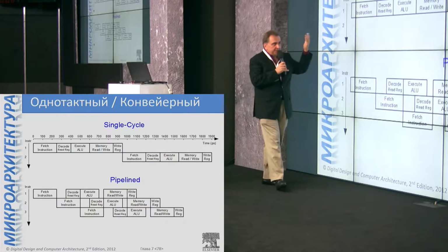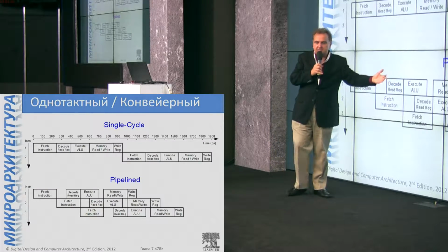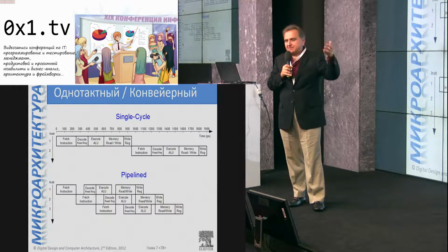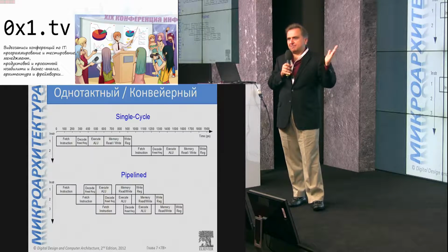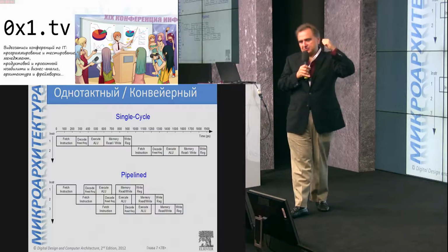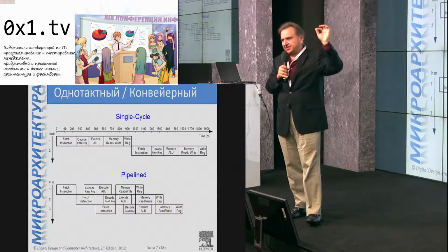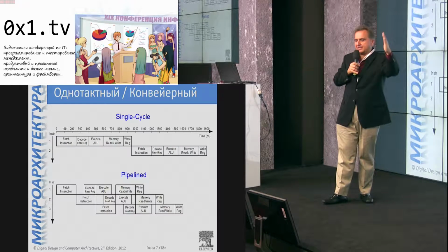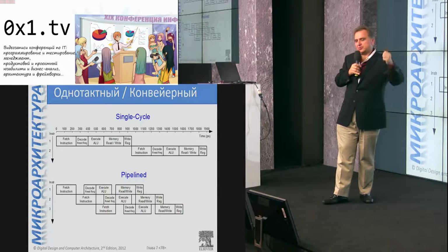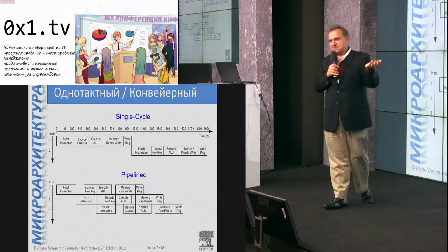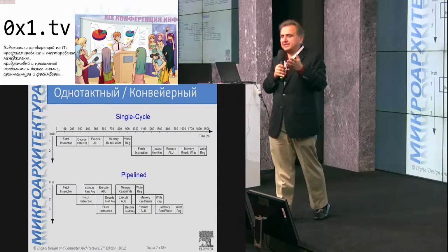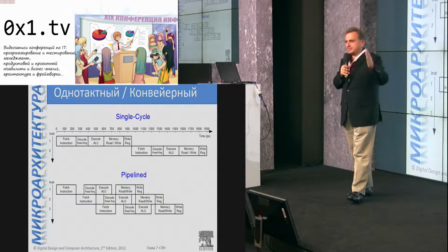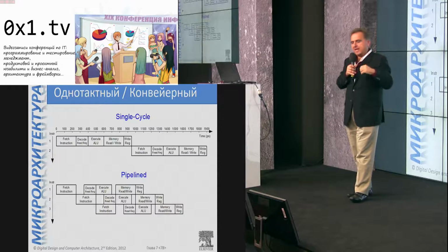organization. So at this diagram, you can understand the concept of the conveyor, of the pipeline in the processor. In the hardware, you have some simple principles. In the hardware, you have a signal of a frequency, and in the hardware, you can describe what is happening inside one round. So you have D flip-flops stored in the processor, and through the language like Verilog, you describe what's happening within one round.